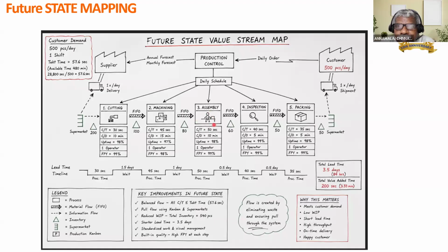Then you will see whether you can add 2 more machines, right? So that the line is balanced. So that may be one of the actions, either increasing the productivity or increasing the number of machines. Line balancing can be the answer if you have a cycle time issue. If the changeover time is taking too much time, you are wasting because of changeover, try to use the other tool called SMED and then try to reduce the changeover time.